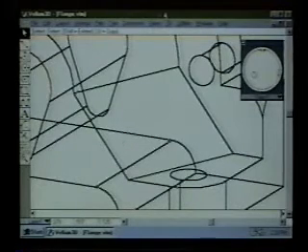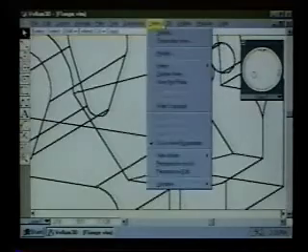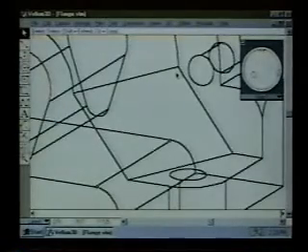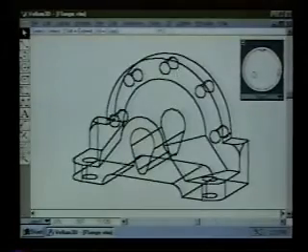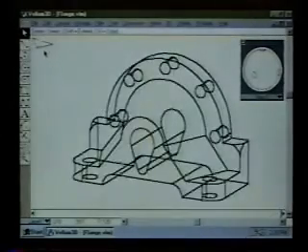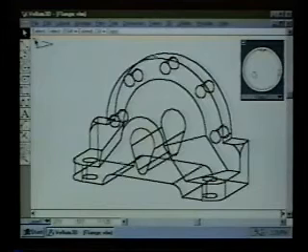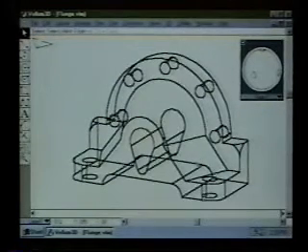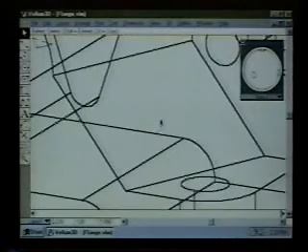And when I do that, I actually can bring up my triad to show that. If I say zoom all here again, just to look for a second, and let me change this over to a wireframe, I have a triad that shows my work planes, and this triangular shape is actually tilted back to match the face of that object. So when I zoom in here, I know that I can draw objects right on there.